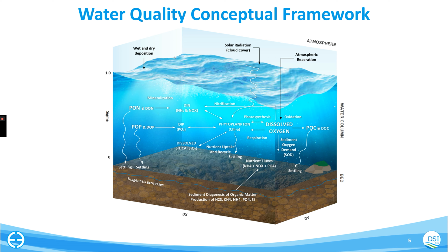But what happens is that your plankton and your particulate organic constituents settle onto the sediment surface. That actually acts as a source term to your diagenesis, and then you have the decay process, and some of that material gets released back up into the water column, but also some of it gets buried permanently, and there's a burial term that you can specify in the diagenesis model.